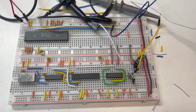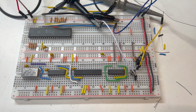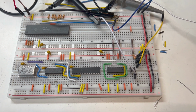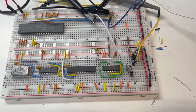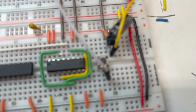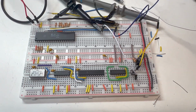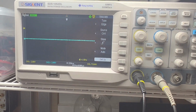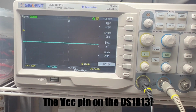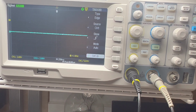Okay, here we are in my messy garage. That's also loud. What we're going to do is watch the reset signals from the little reset circuit you see right down there. We zoom in. There we go. And we're going to watch those on my scope over here. Where is it? There it is. I'm going to connect VCC, and VCC is going to be on channel 2, the blue trace, and the reset signal is the yellow trace on channel 1.